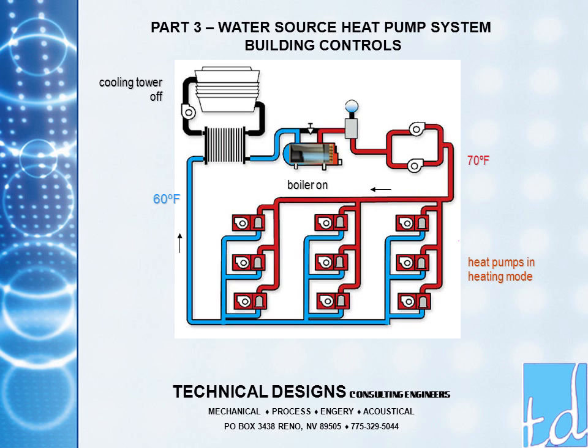Staggering the start of the heat pumps during morning warm-up using a system-level controller can eliminate the need for a larger boiler plant. We can also allow our domestic hot water set point to drift during unoccupied hours and then stage bringing the system back to set point at a time that doesn't conflict with the building heating demand.